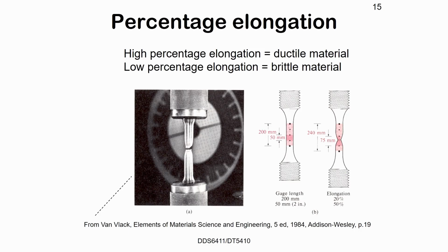So when a material breaks, why does the curve go down? Is it like taking silicone, where as it gets longer and longer it becomes easier to pull apart? Yeah, because you have necking. The cross-sectional area is smaller, so you need less force to keep on increasing the length. But it doesn't mean that the stress is reducing. The stress is actually going up because of the reduction in the area. It's force per unit area.